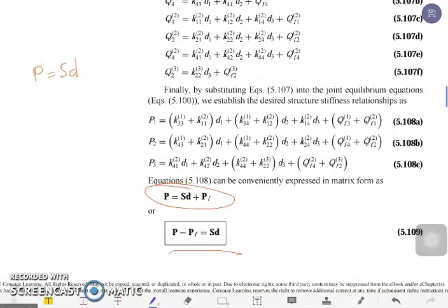So how are we going to identify these? For the joint load vector P, we can easily identify it through inspection based on the original beam, using the external forces acting on the joints. For S, we have to assemble it.